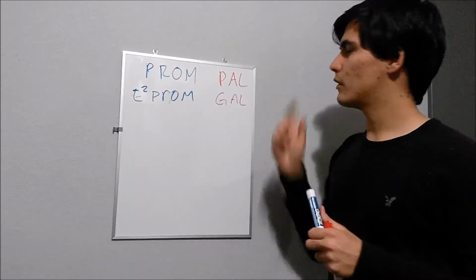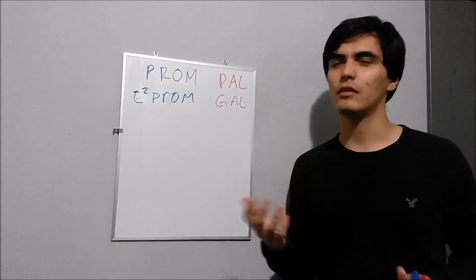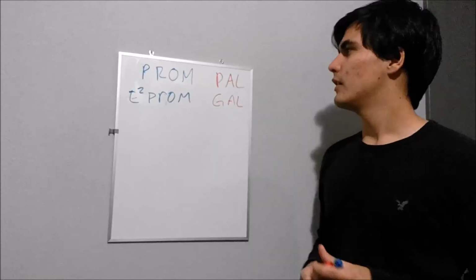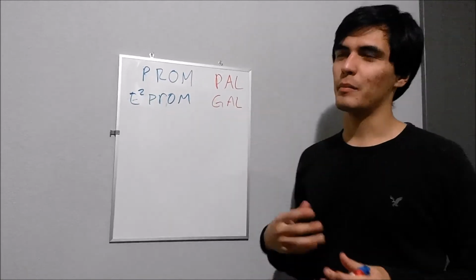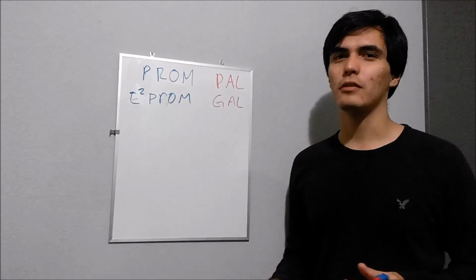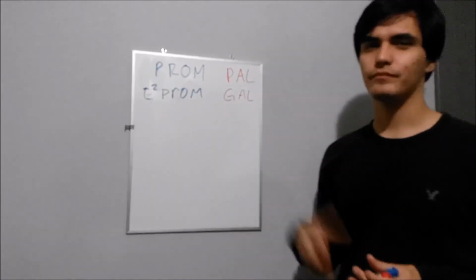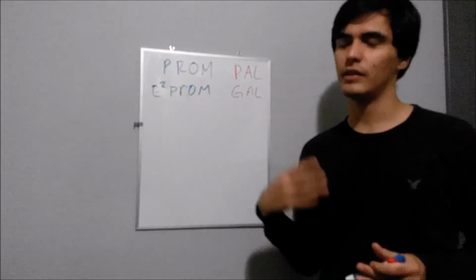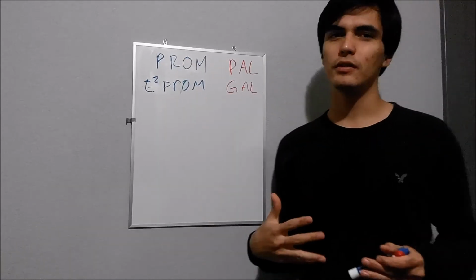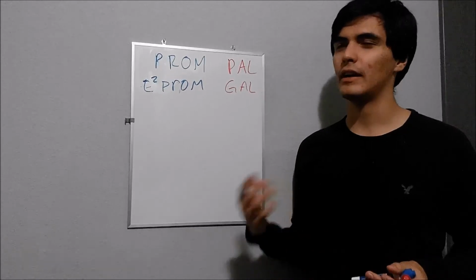So the PAL you can just program once, but the GAL is like a PAL that you can program as many times as you want because it has erasable memory, and you can make the array that you want in the inputs and also in the outputs.